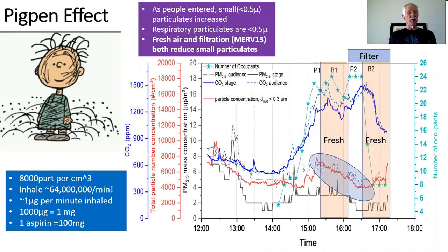The carbon dioxide level went from about outdoor levels of 400 or 500 parts per million of carbon dioxide and rapidly grew with occupancy. And that's because the carbon dioxide we produce from our respiration goes directly into that room air, and it picks up very, very quickly. So even though this is a small fraction of what that restaurant would have on a busy night, it's indicative of how fast the air inside of a building changes. It's not hours, it's minutes. Person goes in that space, the carbon dioxide is going to go up.